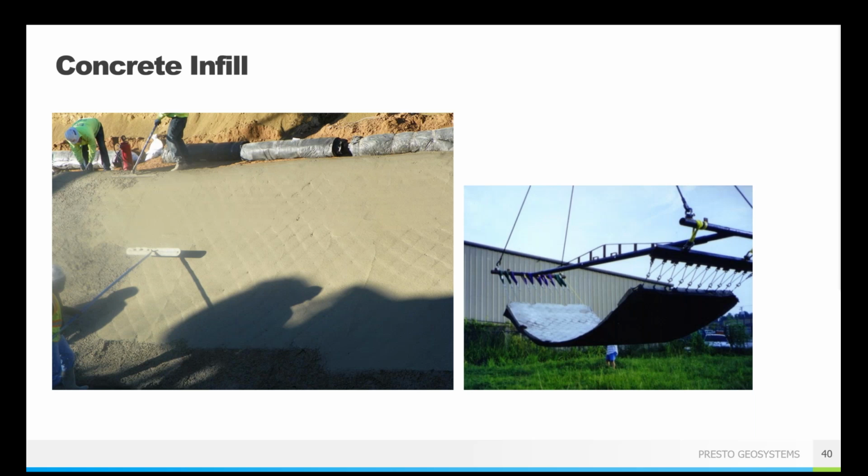And something that is always important with concrete structures is drainage. You do need to still include some sort of drainage behind GeoWeb when it's filled with concrete. Things like weep holes, you can either just drill them through set concrete, or if you want to install weep drainage tubes, those work. Or if you have wicking fabric behind the system, drainage tubes behind the system, something like that. Just definitely something to keep in mind. You don't want to have pore pressure build up behind those walls.